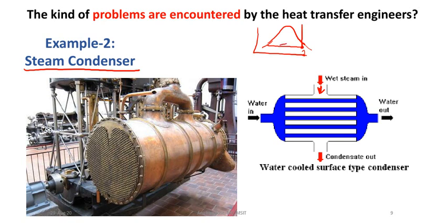Why is it an isothermal process? Because in this process basically only the phase change takes place. Only the latent heat is transferred, and there is no transfer of sensible heat. So from this TS diagram it is quite clear how the process in the condenser takes place.